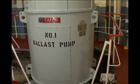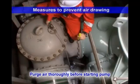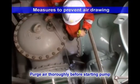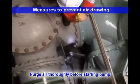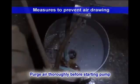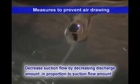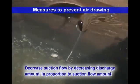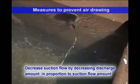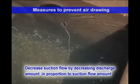There are several ways to prevent air drawing. Purge air thoroughly before starting the pump. To deal with air drawing due to a suction vortex at the bell mouth, decrease the suction flow from the bell mouth by reducing the discharge valve opening to decrease the discharge amount.